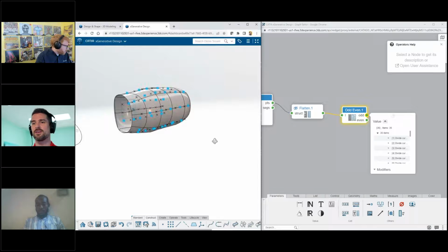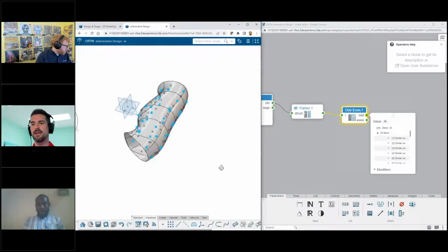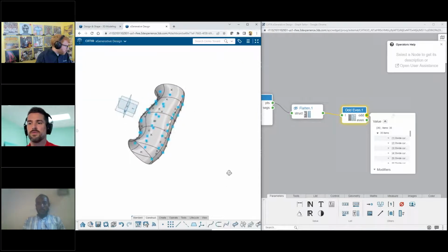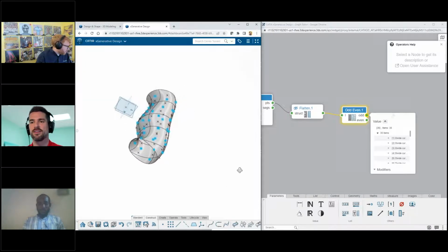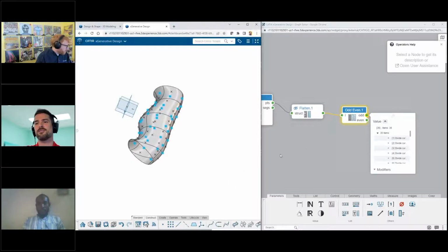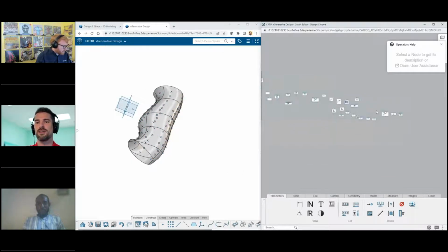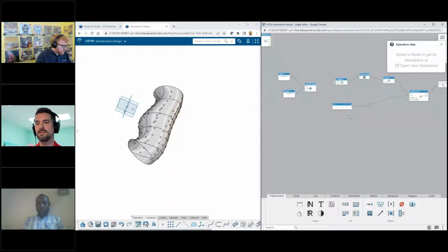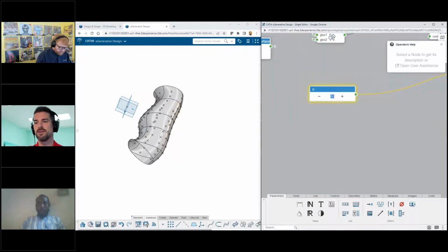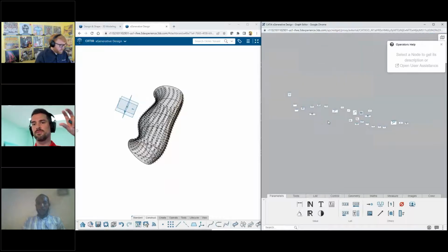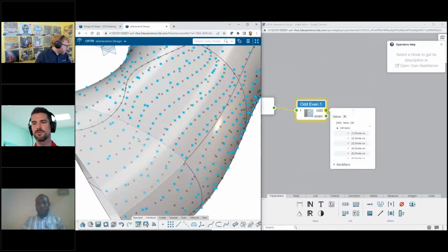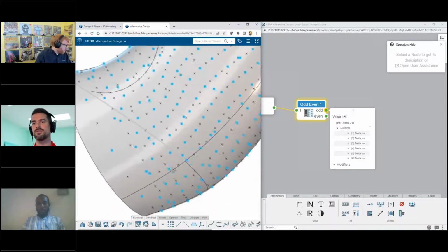It's pretty much like, it doesn't have to respect the chronological order that something was built in. You can connect any node to any other node, which allows for an ultimate level of flexibility. Similar to what I showed with the ordered geometrical set in SolidWorks X-Shape. By dividing chunks of geometry into different ordered geometrical sets, which are basically like folders, they appear as folders in the design tree.